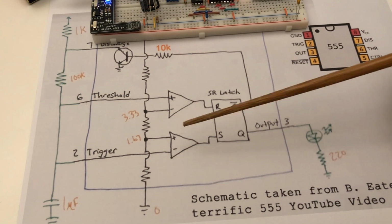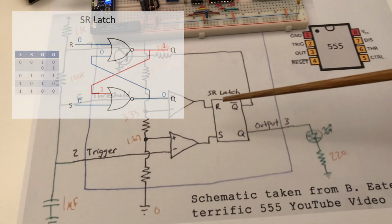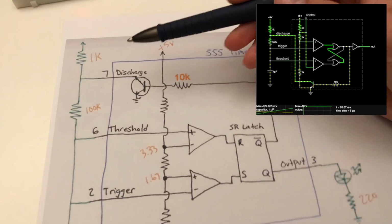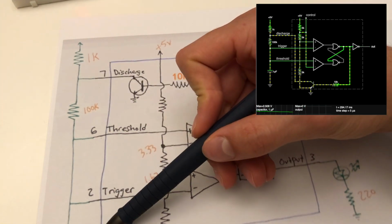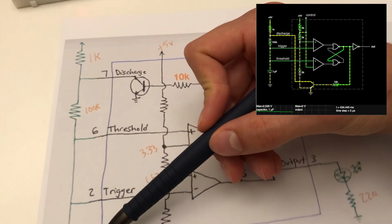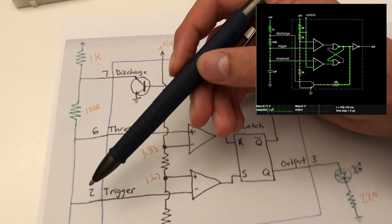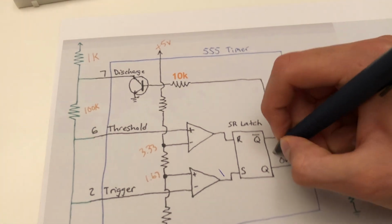The outputs of each comparator are also connected to the set and reset inputs of the set reset, also known as SR latch, which is essential for the oscillation to function. When the circuit is powered, current flows through R1, R2, and then C1. As C1 starts to charge, pin 2 still has a voltage below 1/3 of the source and sets the latch, so the 555 outputs high.